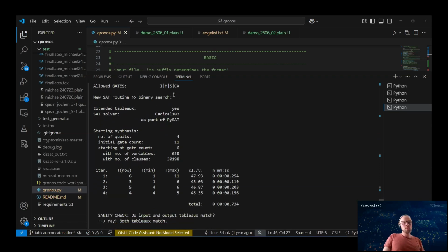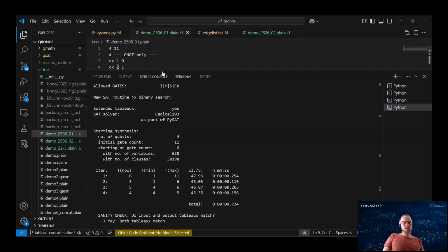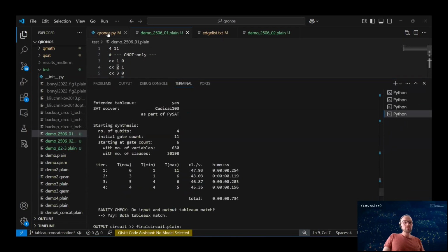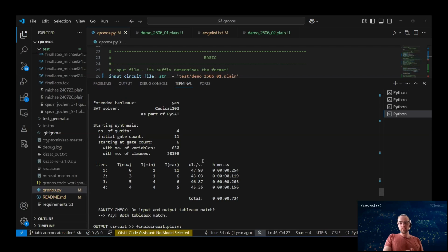And as you can already see here, we had 11 gates in our circuit to be optimized. So we already know, since we do not have routing in there, that the worst solution possible would be the one with 11 gates. So we do not have to check solutions with 12 or more gates, since we already know 11 gates will be the maximum number of gates for this type of circuit. And the binary search, with a lower bound of at least one gate, will then start at the middle with just 6. And apparently it does find a solution which only uses 6 gates. So it reduces the interval that we are searching from 1 to 11 to 1 to 6 gates.